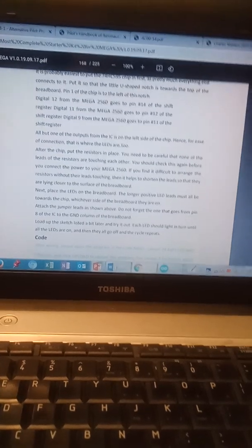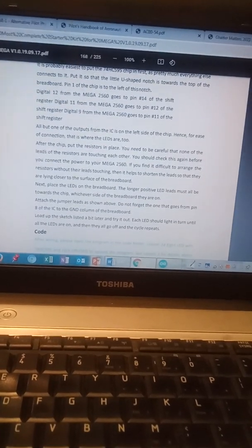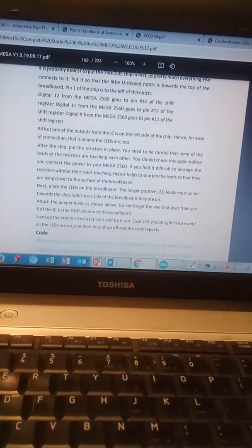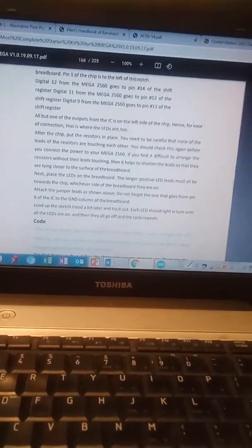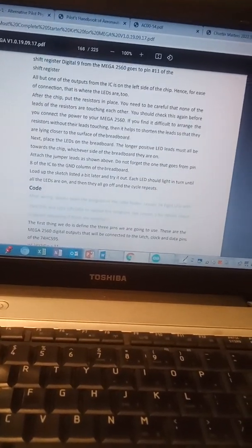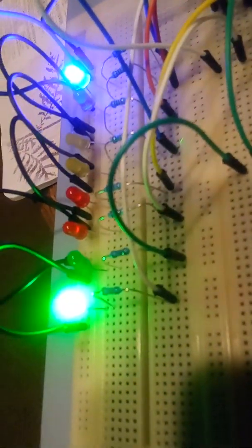And just make sure your wires and your leads, your resistor leads and your LED leads, don't touch, because otherwise you'll short circuit something, you could do damage. So just take your time. I put a lot of spacing in mine. You can see it now that I'm showing you, and you can see the latch and the gate.